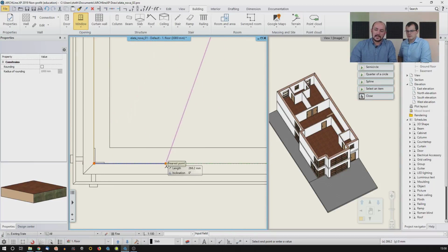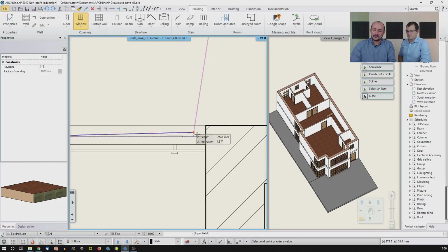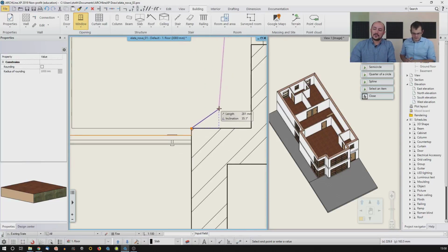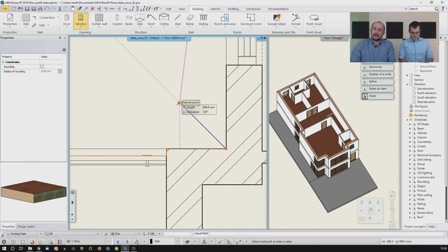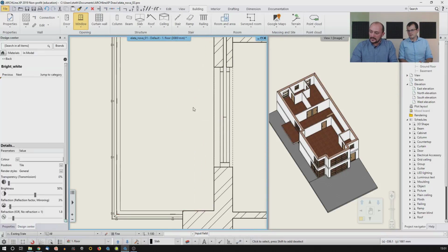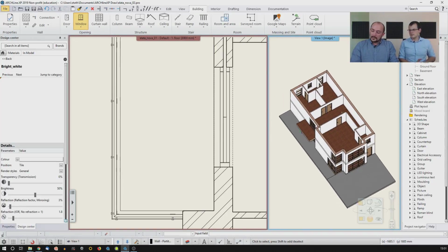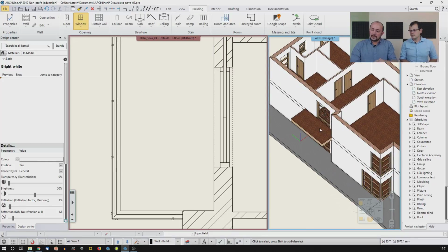If you make a mistake, don't worry, you can just misclick somewhere, undo that, and later the slab is actually flexible enough to allow you to change its contour later, just as in case of the ramp, we did that. So it's not a problem if you are not doing the perfect job for the first time. You can change the contour later as well. So now I'm done with the contour. I just hit enter, and now I end up with a balcony with the proper size, but not with the proper perfect settings, because I didn't set them previously.